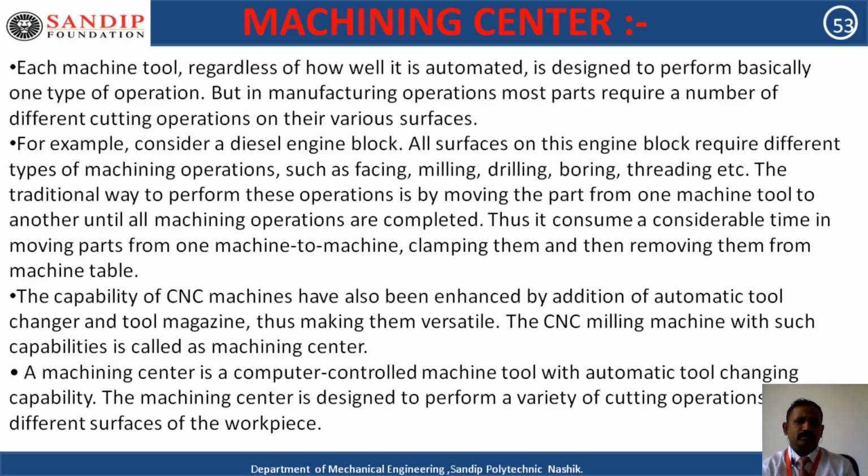In machining, the tool always moves in position along the coordinate axes x, y and z. In a lathe machine there are only two axes, x and z, and z is always the rotary action or spindle driving axis. In milling there is also x and y, sometimes z also, and drilling operations also. So in a lathe machine there are only two axes, that's why it is called a two axis machine.